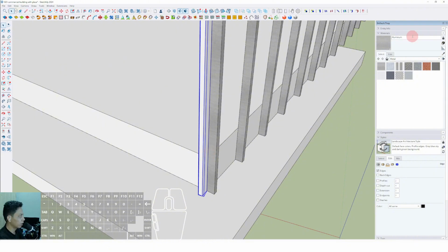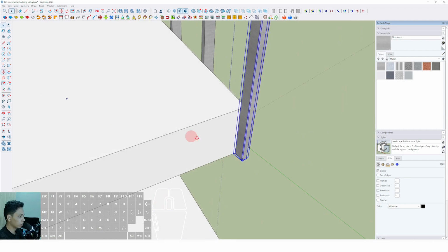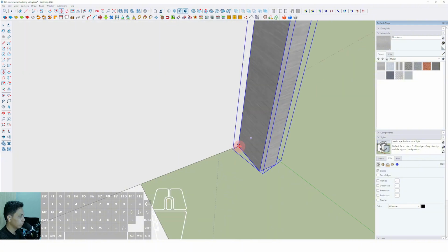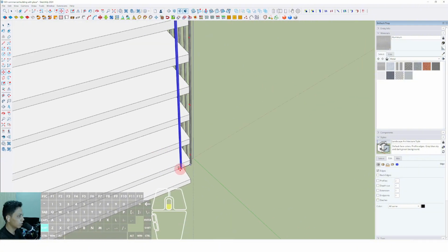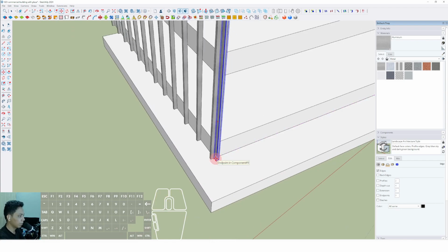We can triple click, right click and make group, and we can assign the material. Then right click and make component, create, then select move, press Ctrl, then we can place it in the appropriate position on the left side over there. Then we can type, for example, 20 slash and enter.